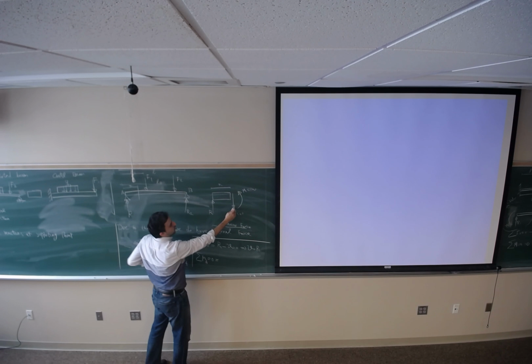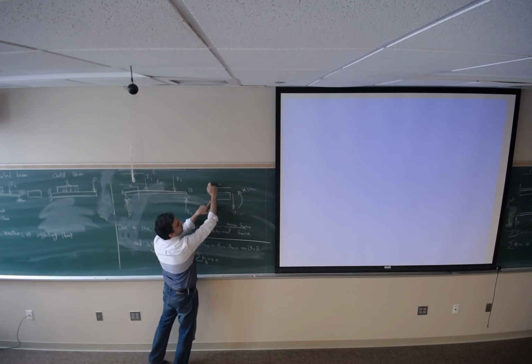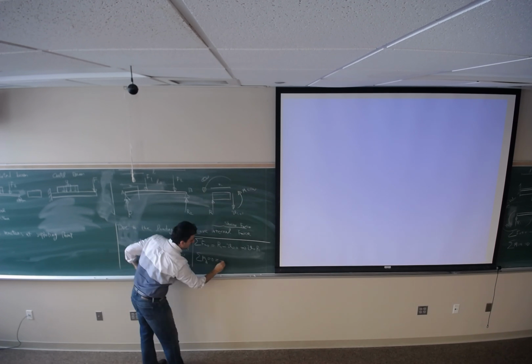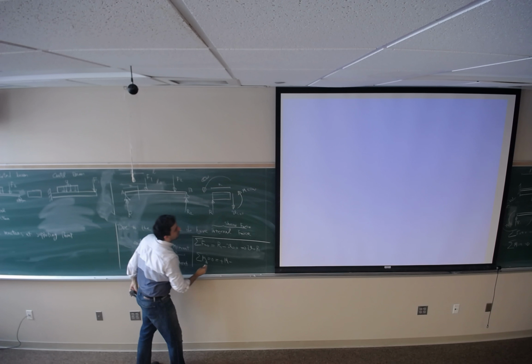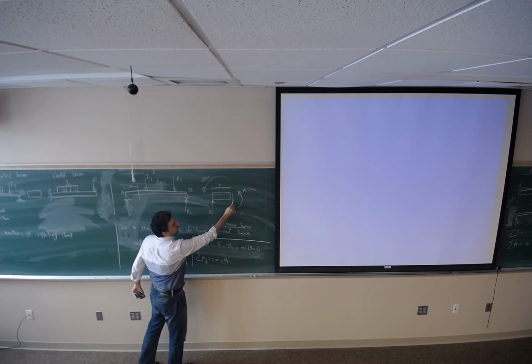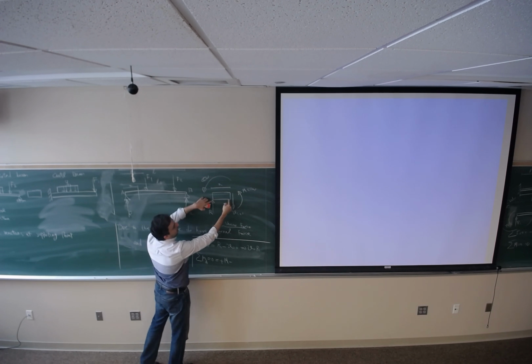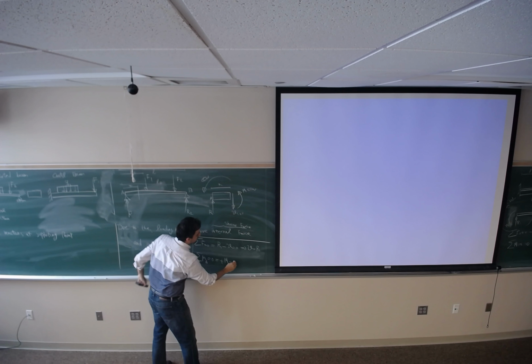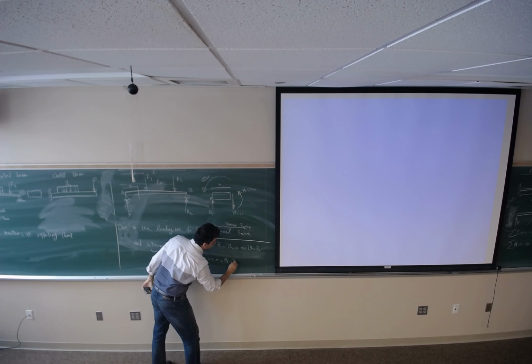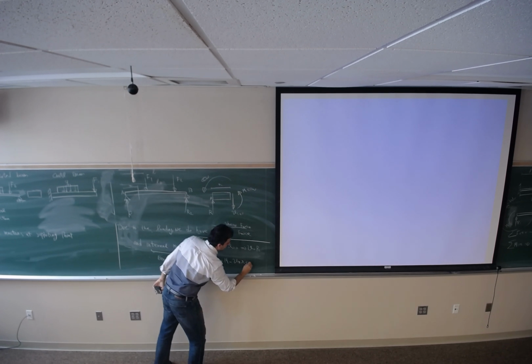What do we have? We have positive M because it's making counterclockwise rotation about point A. And this force times the distance from point A is making a moment in the opposite direction, which is clockwise. Negative V times X equals 0.